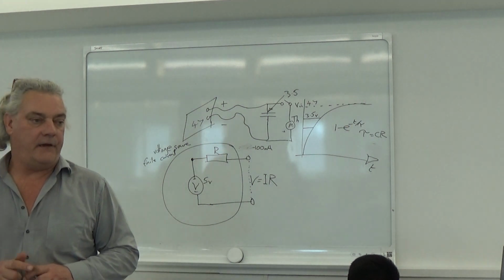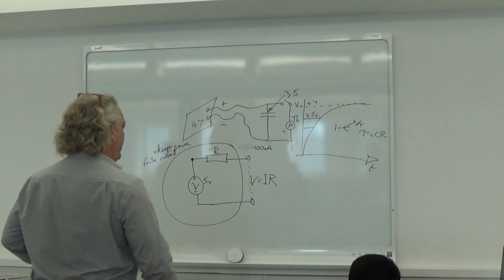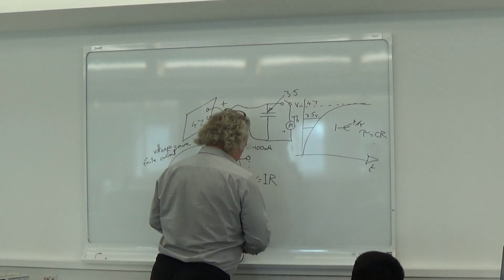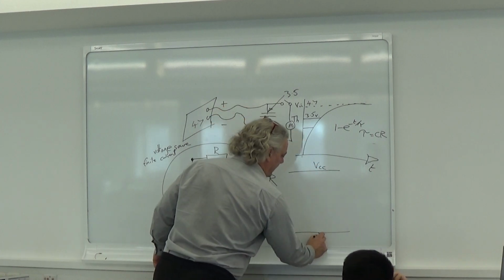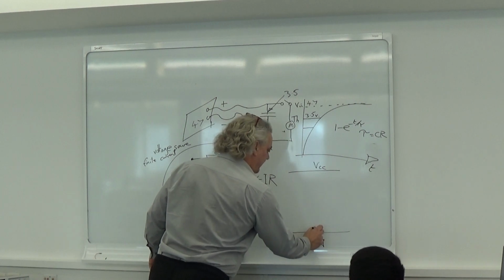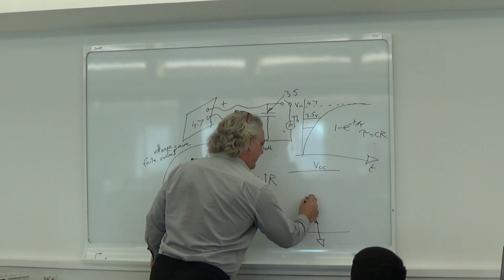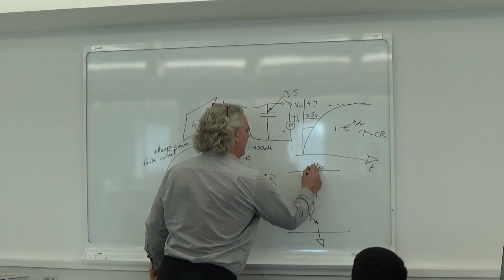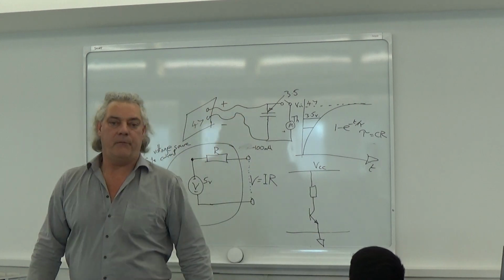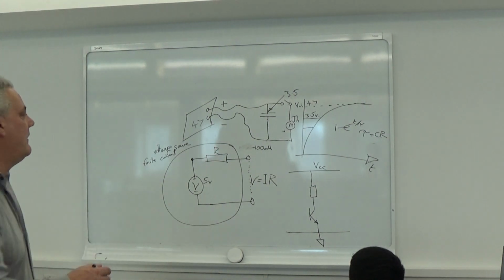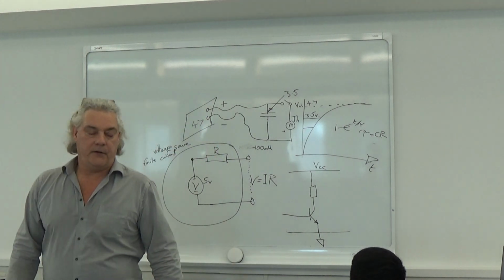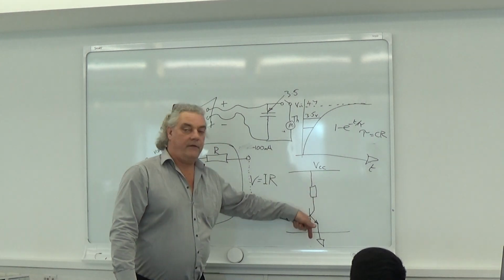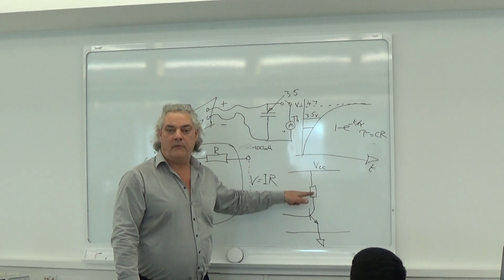Now, also something that you need to take into consideration, because what people are doing, and many of the circuits are the same, so you've got your output chain. So here's your VCC, here's your ground. And what many people are doing is they've got a transistor here, which is a perfectly sensible thing to do. And they don't have a motor in Multisim, so they use a resistor. But by putting a resistor there, if I turn that transistor on, current's going to flow from here down to here, isn't it? What do you think that's going to do to what I measure across here?